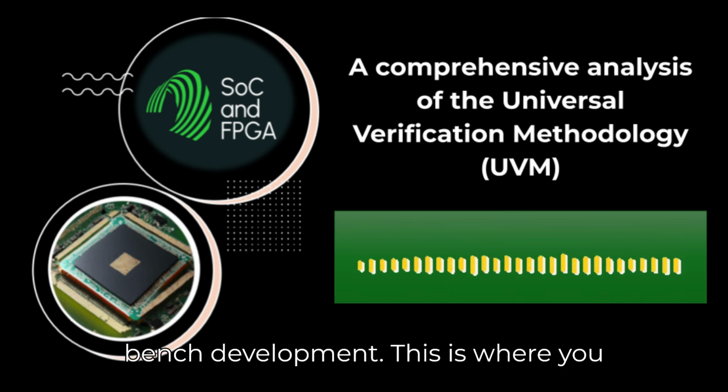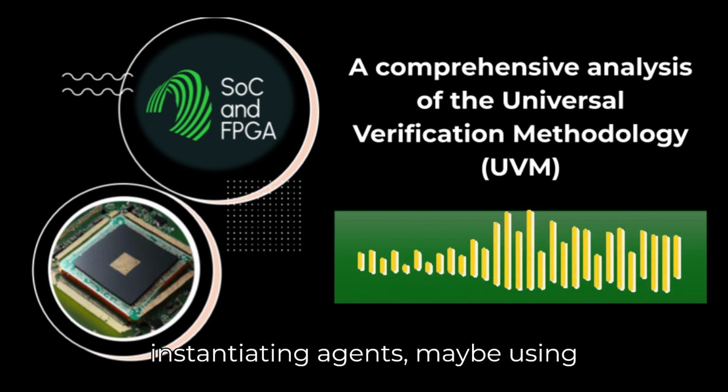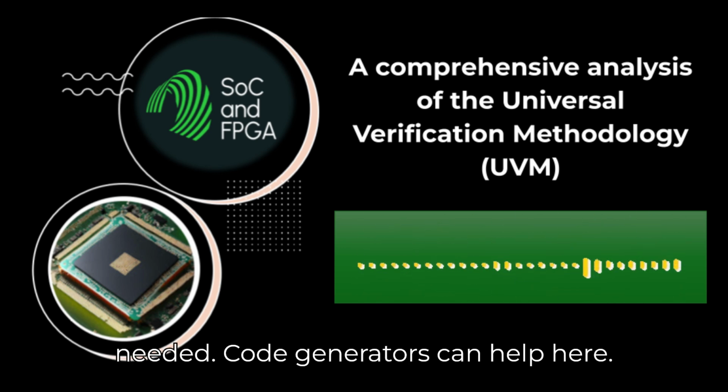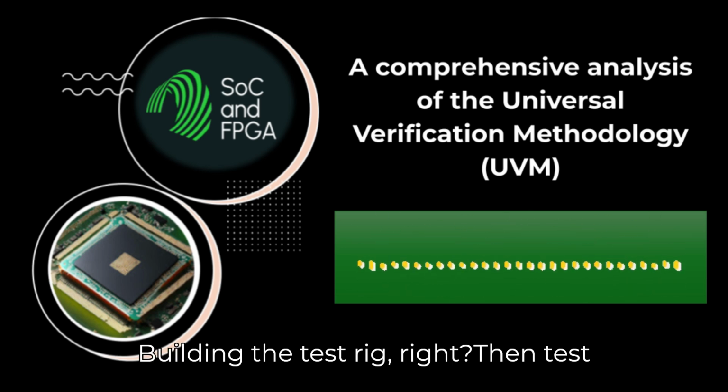Then comes test bench development. This is where you actually build the UVM environment, instantiating agents, maybe using pre-built VIP, connecting them, building the scoreboard, the reference model if needed. Code generators can help here. Building the test rig. Right. Then, test writing.